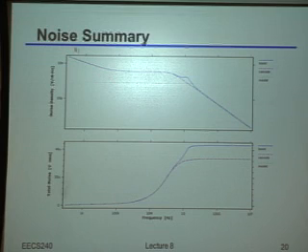You can see there's a 1 over f component down here, and some white noise. Then you see that you maybe pick up a little extra noise from the boosting circuit, but overall it's very comparable to the original cascoded current source. You can't even really see the green line, because it turns out to be almost right on top of the pink line. This bottom panel shows the total integrated noise from 0 to whatever frequency is listed on the x-axis. It shows there is some small penalty in the noise, but typically not too substantial, especially if you've done this the right way.